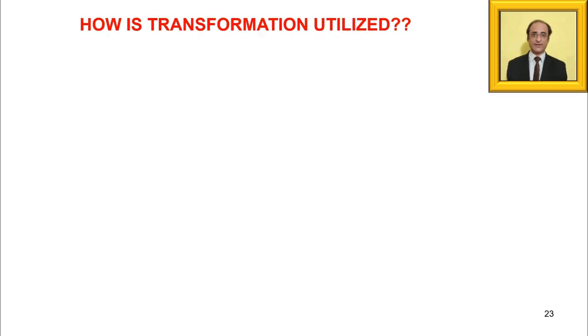Now we begin with a member first, because we are dealing with finite element formulations. So we first enforce the relationships for a member. Essentially this basic equation includes both the compatibility and the equilibrium conditions for the member.